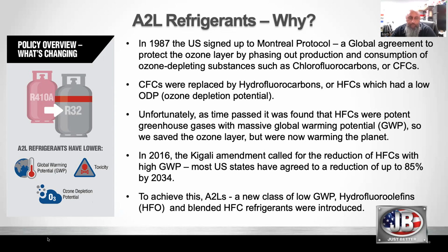So why A2L refrigerants, right? So we've been through that. There's the Montreal Protocol in '87. That was phasing out of CFCs. They were replaced by HFCs. Again, we spoke about the zero ozone depletion. We spoke about the fact that they had high global warming potential. So in 2016, there was an amendment to that original protocol, which then called for the reduction of HFCs. And that's why we've seen 410A moving to those new A2L refrigerant classes.